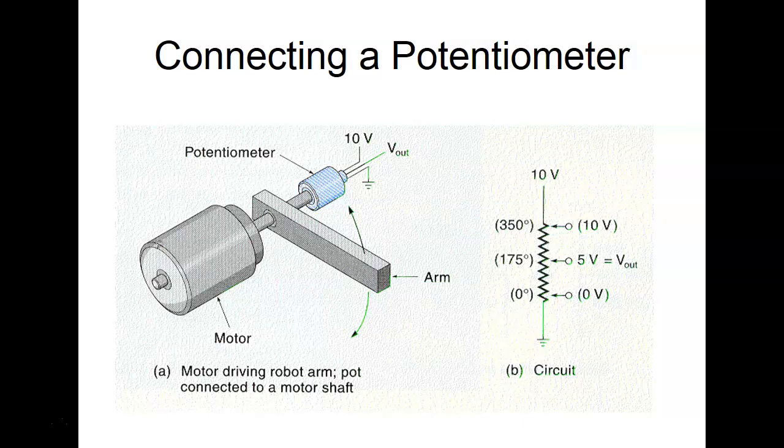So what would be the transfer function on this? We got 10 volts. We need the size of the pot. No, we don't. By the way, the actual ohm value of the potentiometer is not really relevant, but the bigger the pot, the more ohms per degree, which means it's going to be harder to set it, right?